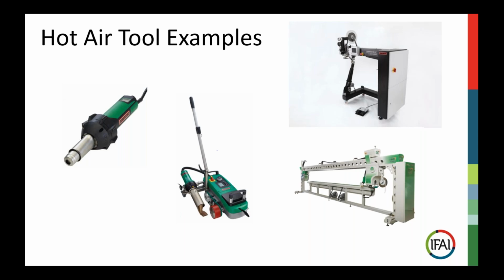It's the most basic type of hot air welder. From there, you could progress to an automatic welder. That's also known as a robot or a machine that moves. So you could put a welder on a long table, on the floor if you're welding extremely large panels. And that pressure and heat come from the machine itself.